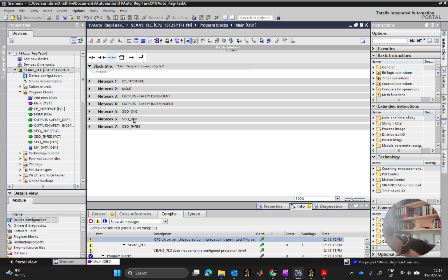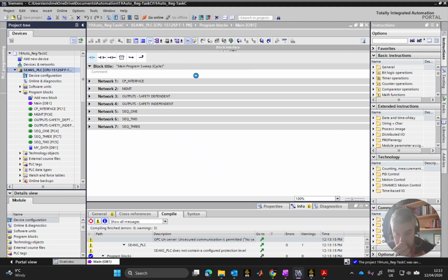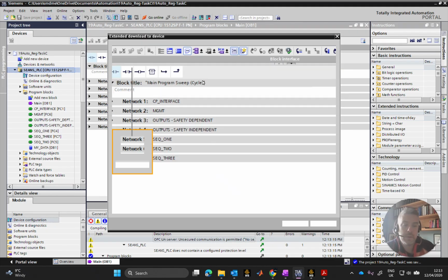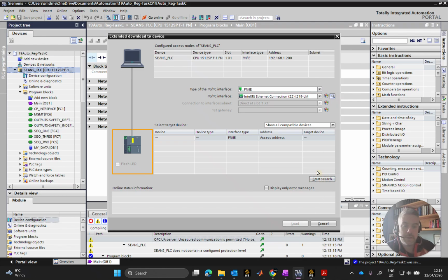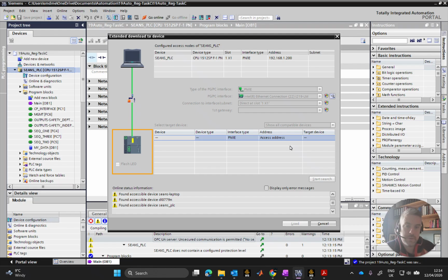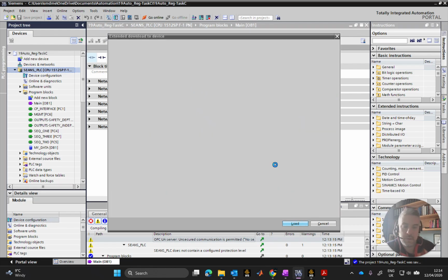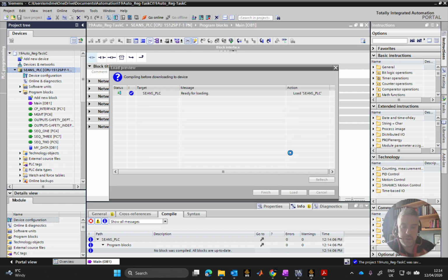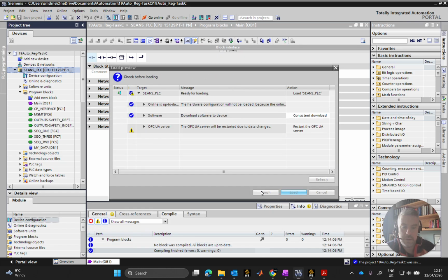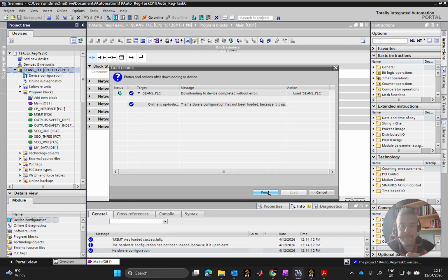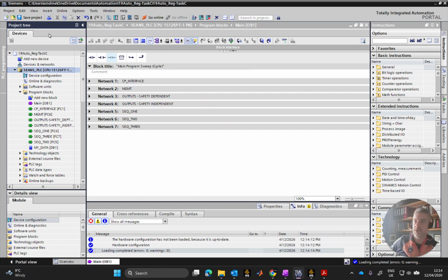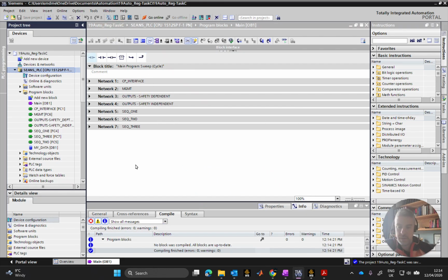And let me just plug in an Ethernet. If that's all good, then let's download that into the PLC and just make sure that that will also work. Okay, start search, and I'm looking for 200, which is there. Load that. We're going to have to synchronize, load, finish. That's it, done. Save. All right, job done. So there I can compile again after I've done that. If I compile, there's the warnings away.